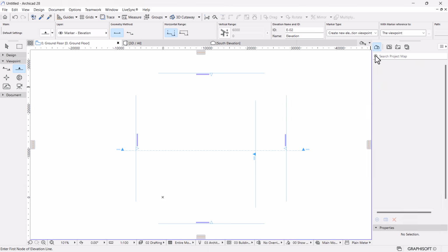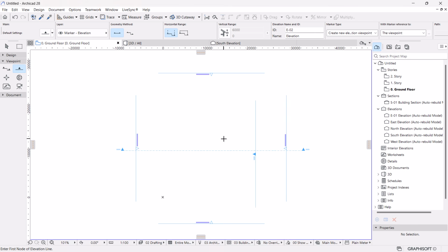So from the project map, whatever you draw, whatever you place, whatever you design is going to be listed or captured in the workspace. But then now, if you want to filter and separate elements accordingly, for example, if you have an equipment and furniture layout, you have electrical and ceiling layout. These are two different drawings that need to be separated.